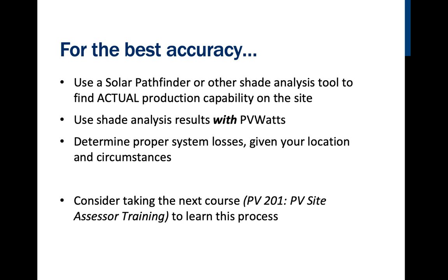And that one is highly accurate as well. When you use PV Watts and a Solar Pathfinder or a shading analysis tool together in tandem, it makes a highly accurate prediction of what the system will produce or how much you need.